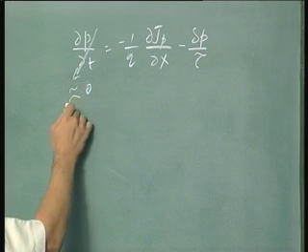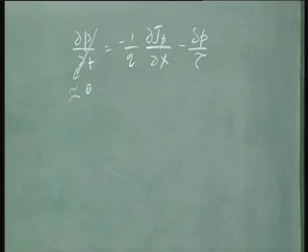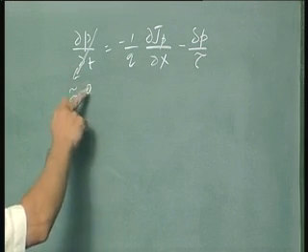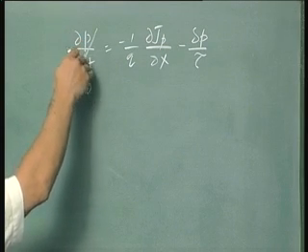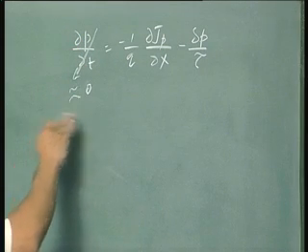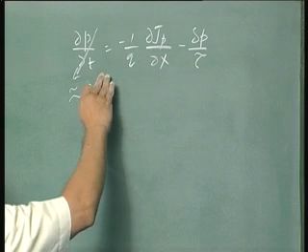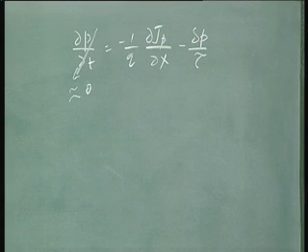So this approximately equal to 0 means quasi-static. Please note that strictly speaking dp/dt when the conditions are varying with time is not equal to 0. That is why strictly speaking the distribution of the holes will not be exponential.